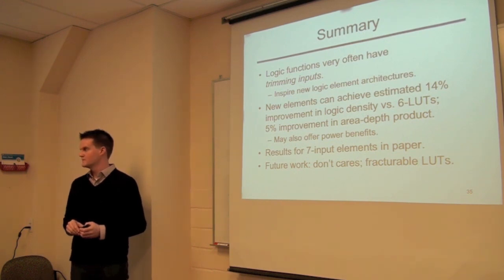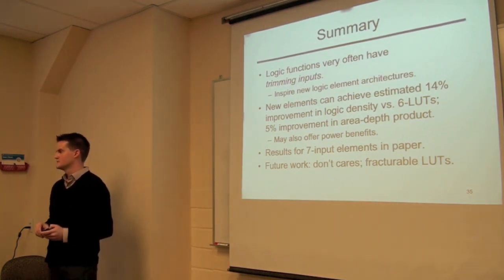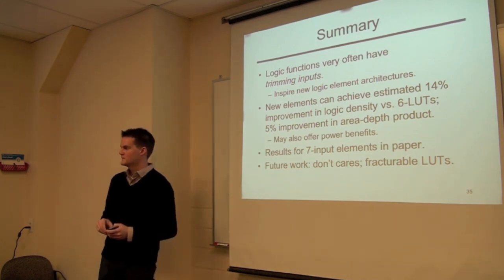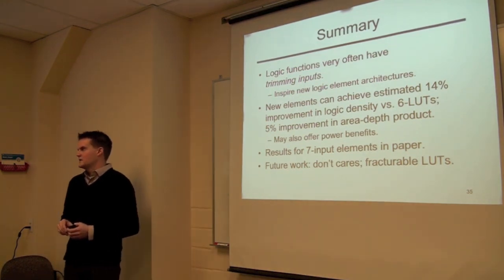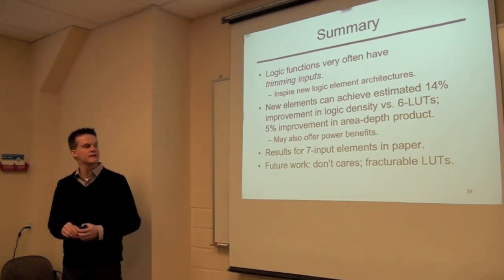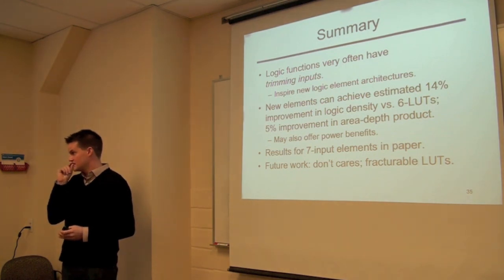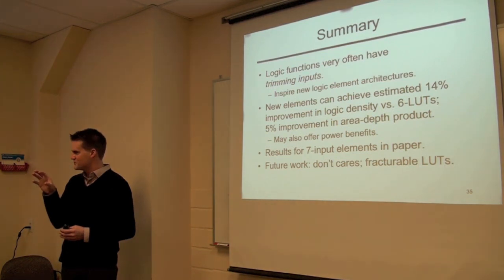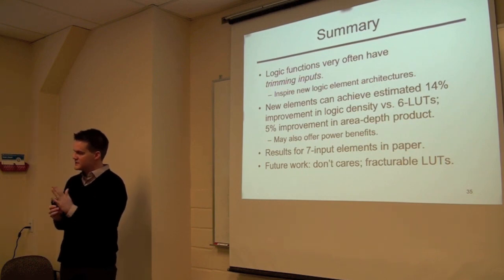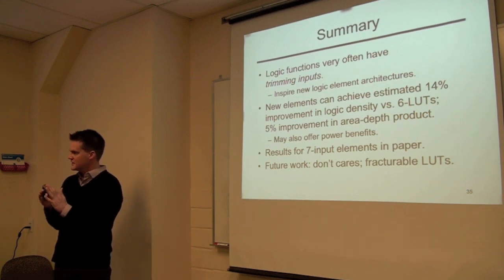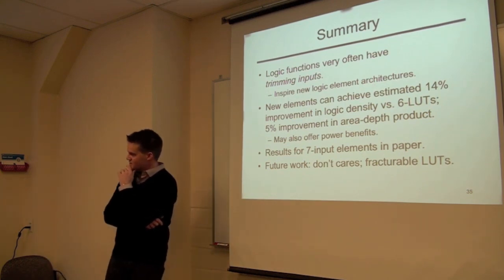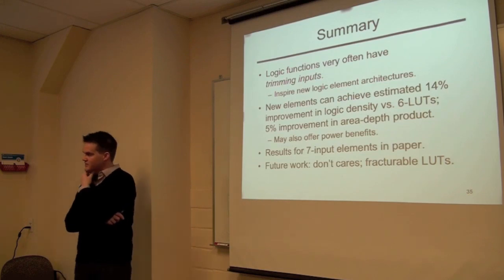Could you run through VPR 5.0 to measure the impact of the fact that your LUTs are less rotatable now? Basically just make fewer logically equivalent pins and just model it. We could do that, yes. So, VPR 5, if you target a cluster-based architecture, assumes the full crossbar within the cluster. So once you hit the logic block, it was a full crossbar to hit any LUT input inside there. Wouldn't you have to have routing up to the LUT input pins or something to properly investigate that?